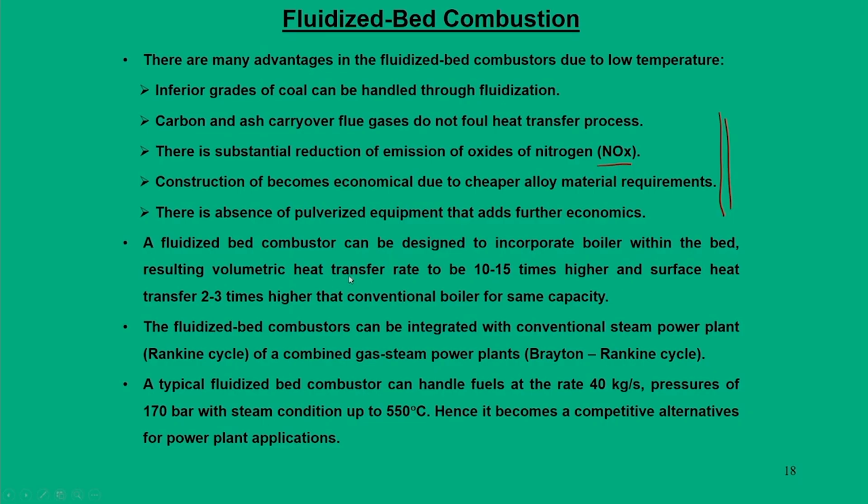The fluidized bed combustors can be designed to incorporate boiler within the bed, and through this fluidized bed technology, the volumetric heat transfer rate can be increased about 10 to 15 times, and at the same time surface heat transfer rate is also higher by 2 to 3 times as compared to conventional boiler technology.